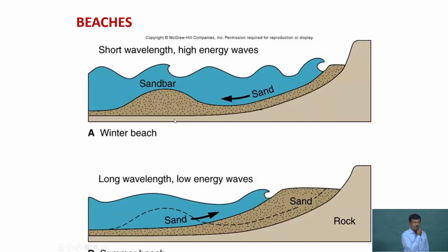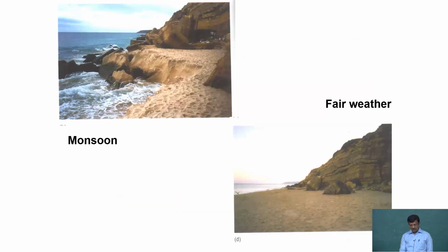Non-monsoon waves always work to replenish the particular coastline, and this is a typical state that we can see at many locations across India. The Kerala coast is a very common sight. There will be a steep cut during the monsoon, and no wonder within the next few weeks after the end of the monsoon we will get a very good beach back. Okay. So, the steep cut is due to the so-called onshore-offshore sediment transport.